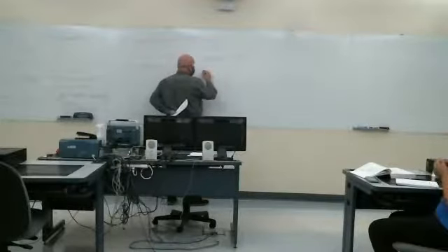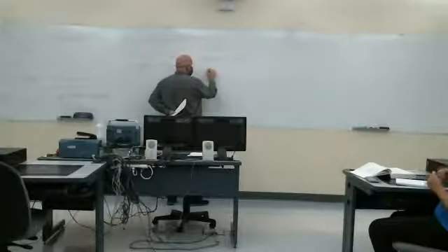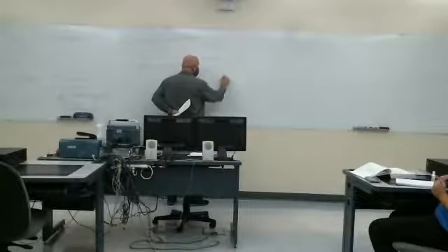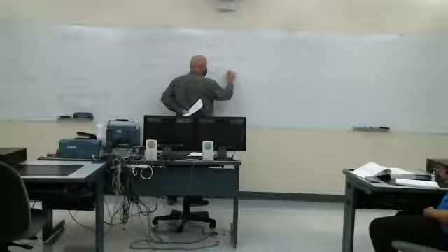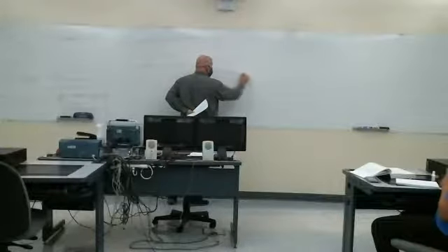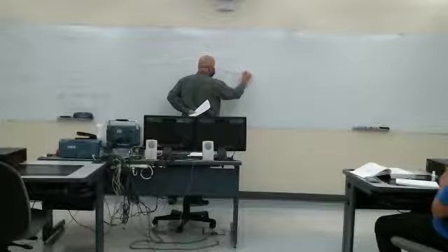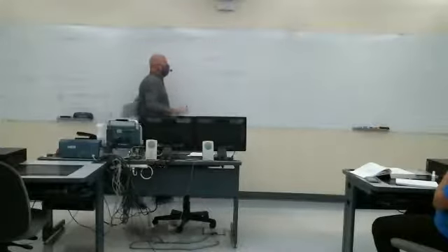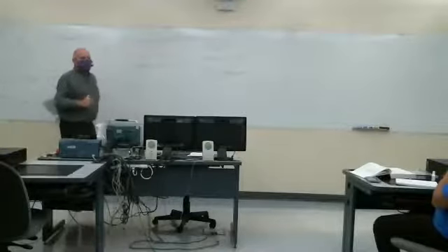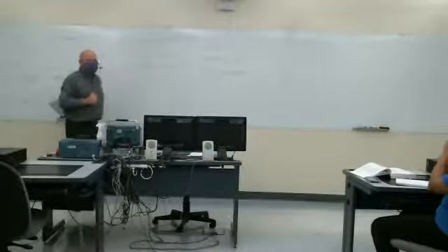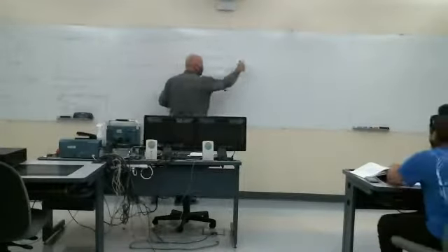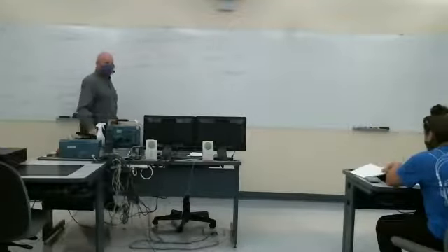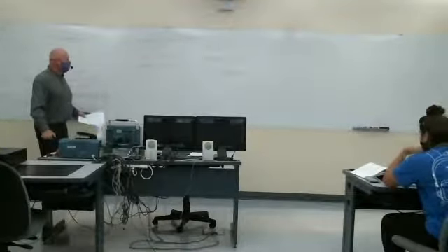If that's exactly the same as running my original x1 through the same system and then scaling that output, so this is y1 of t, this is amplifying by c, this is cy1 of t, and these two are equal, then the system satisfies the scalability property.